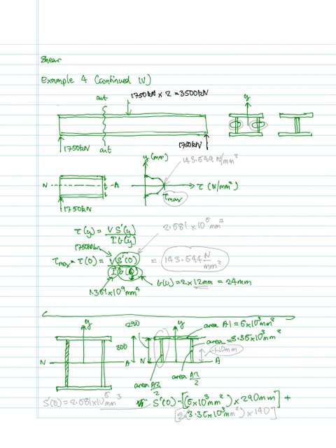So draw a dotted line across there, and we know that the total depth is going to be 300 millimeters, and the thickness of the top plate is 10 millimeters, so that distance there is going to be 290 millimeters.